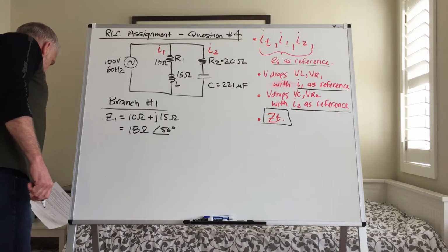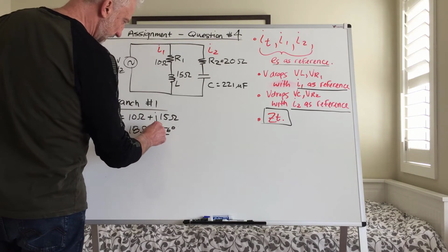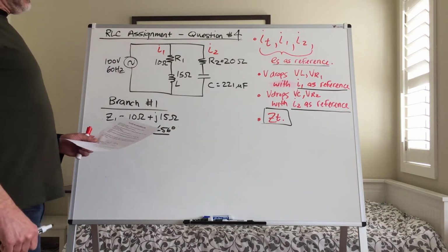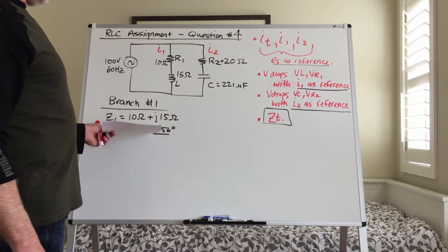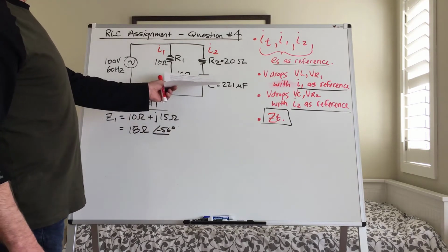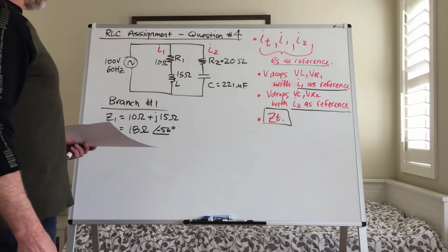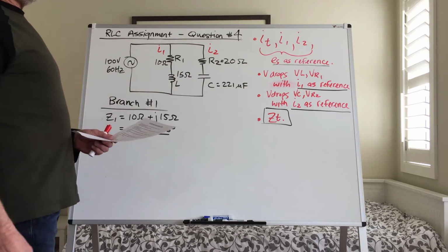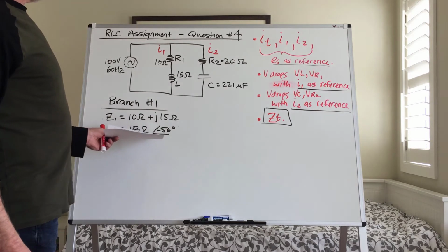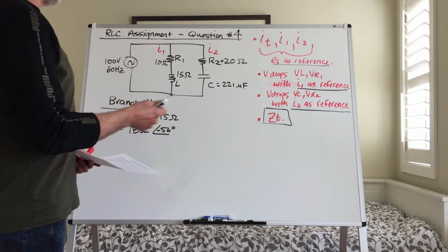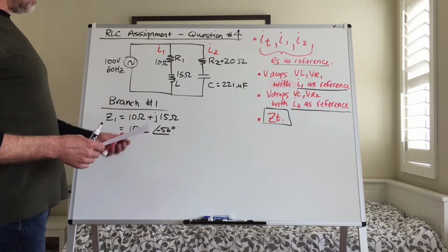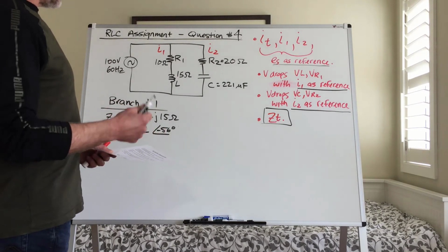So that means, oh, and I'm sorry, I didn't include my negative angle in there. When it comes to phase angles, you don't need to include polarity. Calling this 56 degrees and calling this also a positive value is not incorrect, but in my analysis, I always include this polarity because I think it helps sort things out when it comes to identifying by your calculation whether it's inductive or capacitive.